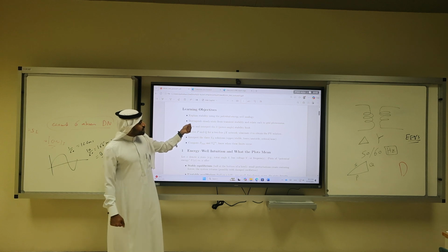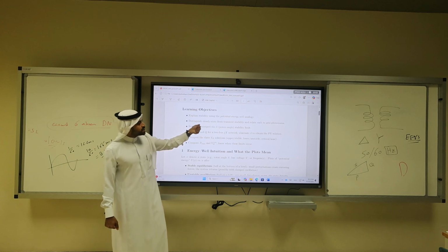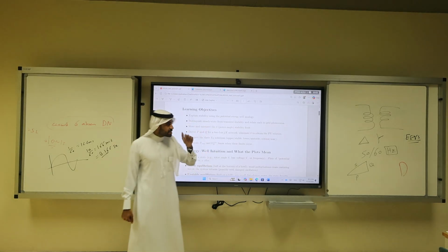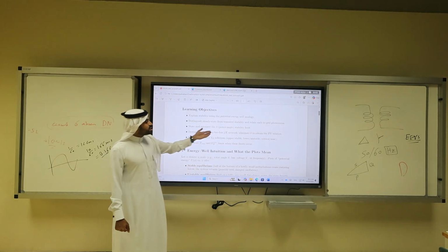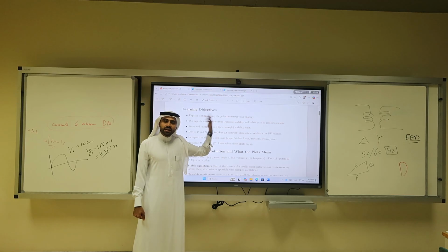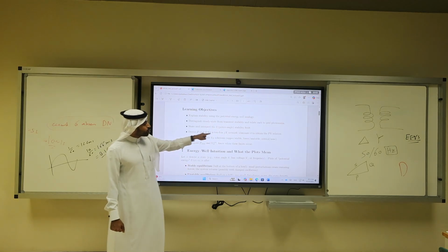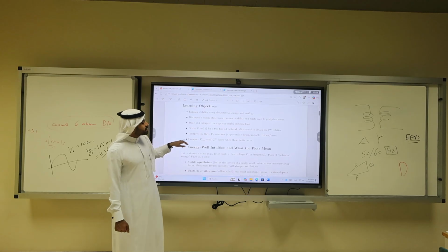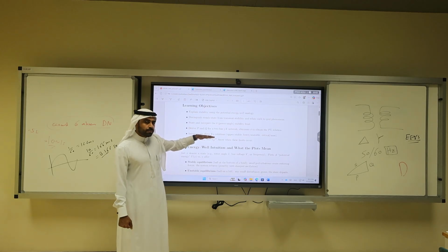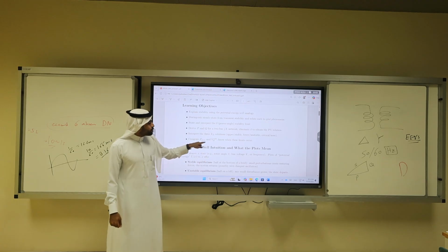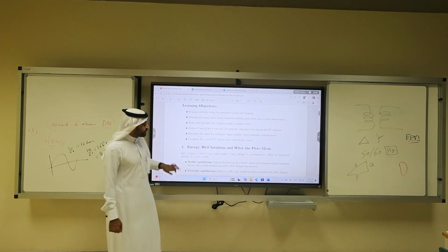The second concept is we need to distinguish steady state from transient. That's very important because we're covering steady state. And what is the power angle and stability limit in a power system? We need to derive P and Q for a 2-bus network, and solve for VB at bus B, with buses A and B, as well as compute the maximum and the critical voltage level.